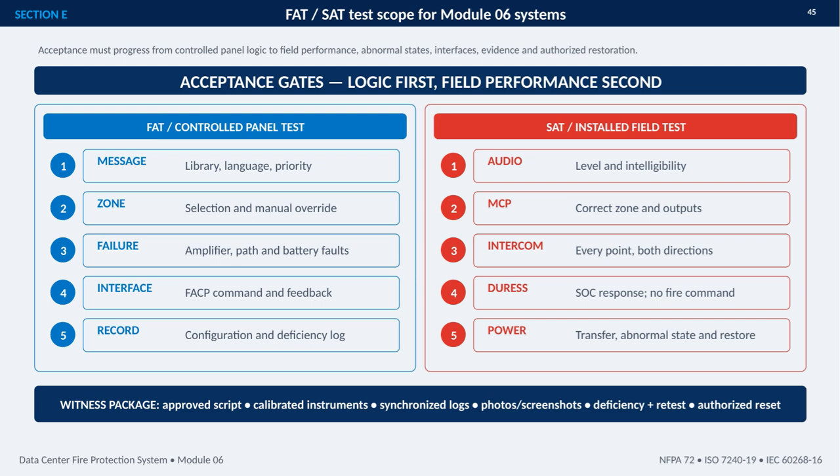The witness package ties the process together, using the approved script, calibrated instruments, synchronized logs, photos or screenshots, deficiency and retest records, and documented authorized reset. This evidence supports acceptance against the reference standards.